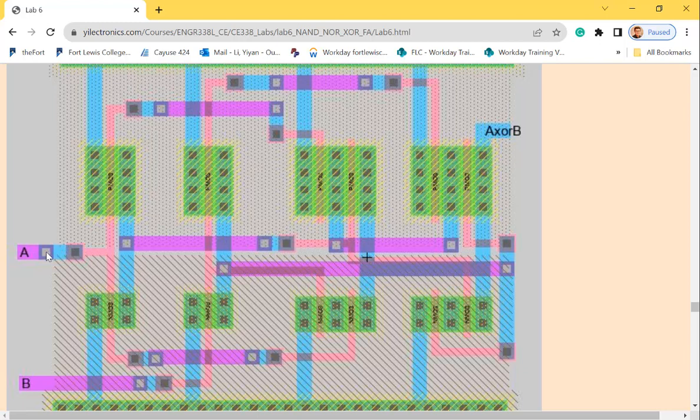And what is this? Yes, a via, but this via is metal one to metal two. So the purple trace is metal two. Right after that, I got a via connecting to metal two. So I'm actually routing the signals in the metal two layer. Since you only have 3 metal layers, it's better to have one type of trace interconnect all the transistors or give signals in a different metal layer, and keep all the metal traces inside the transistor that connect drains and so on in the metal one layer, so it's easier to route signals.